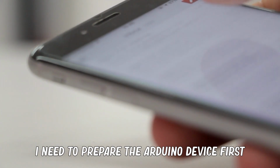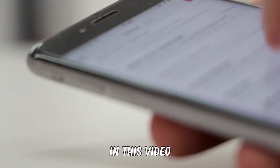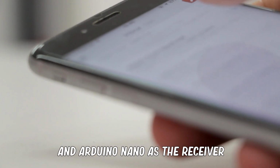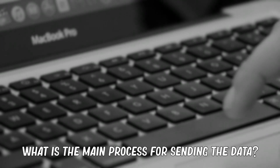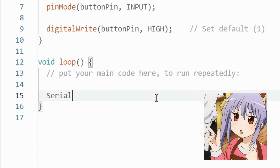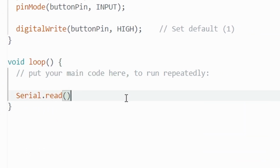I need to prepare the Arduino device first. In this video, I use Arduino Uno as the sender and Arduino Nano as the receiver. This is up to you. Then what is the main process for sending the data? In this video, I didn't use functions like Serial.write or Serial.read. I just used basic functions like digitalWrite and digitalRead.